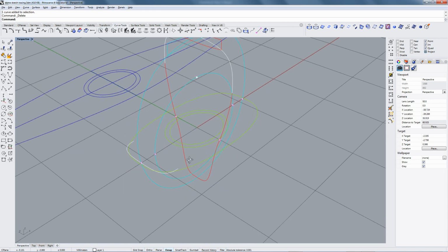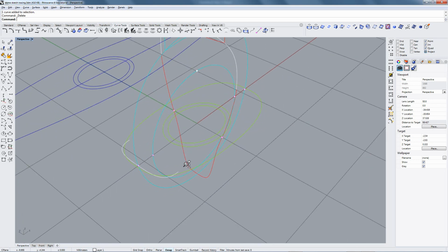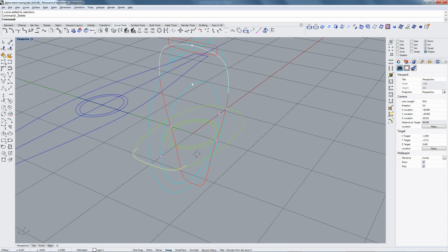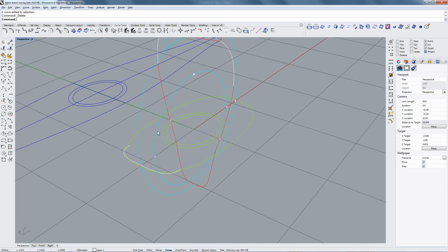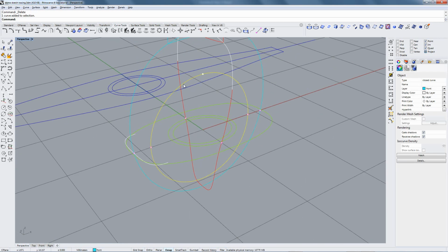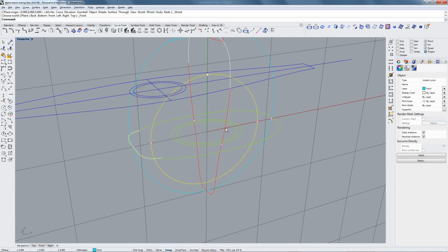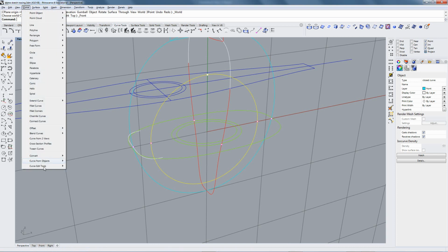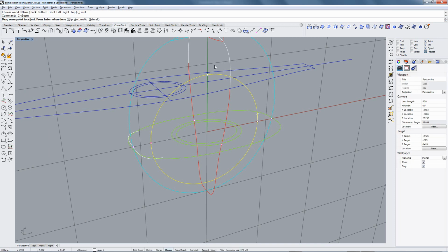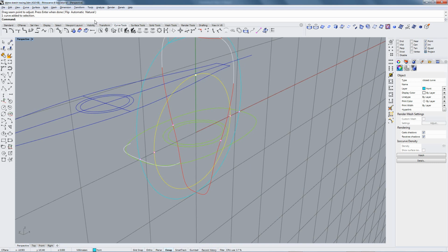Now I need a rail that I can use. Going to take it. Now I have a circle here. In Rhino, whenever I have a circle and I'm doing a ring, I want the closed curve seam to be at the bottom. So I'm going to go ahead and check that now. There we go. And I'm going to copy this.